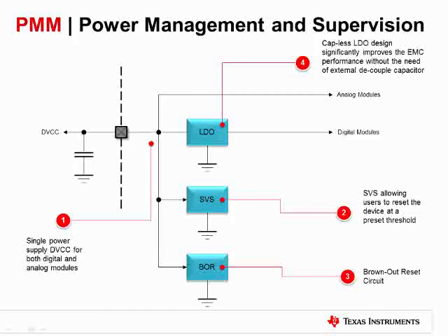The PMM also houses the internal reference voltages. The reference is automatically turned on or off based on your operating mode. The internal reference can be used to generate 1.5 volts for internal reference, such as with an ADC, or it can output 1.2 volts externally on a pin for external use. There are also bits to indicate the reference status so that you can tell if it is ready to use, and you can manually enable or disable the reference.